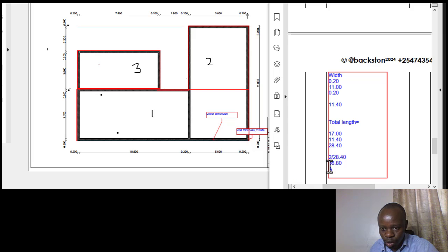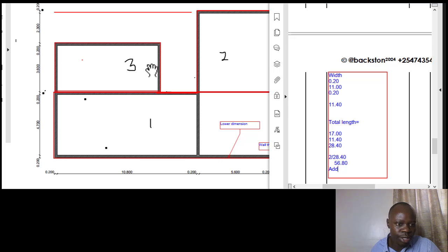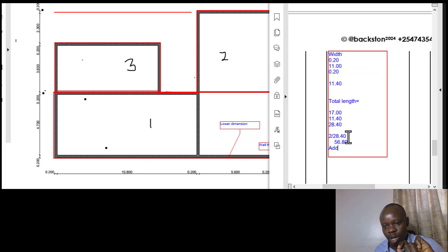Okay, and then we are going to add the recesses. And the recesses, we take them to the external face, so it will be 0.2, and then we add 3.6, so that for the recesses on either side is going to be 3.8 times 2, 3.8 on one side and 3.8 on the other side from the external face as well.